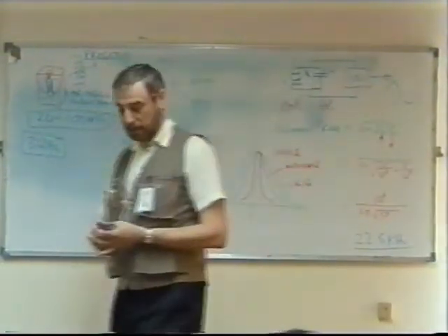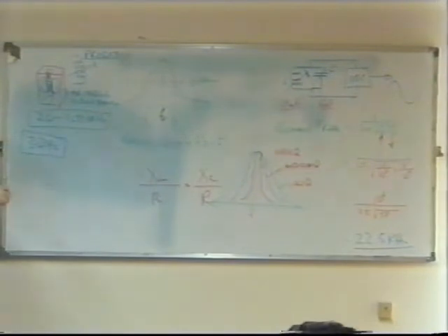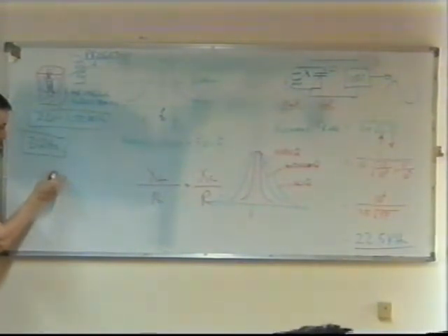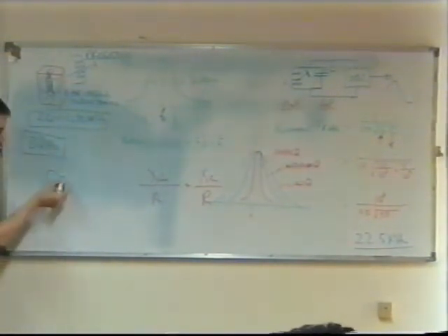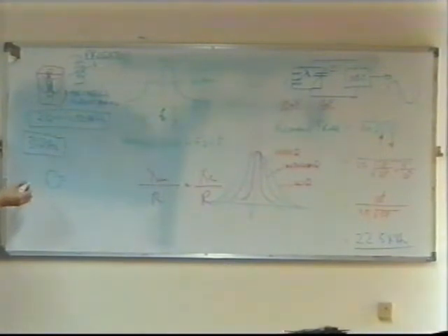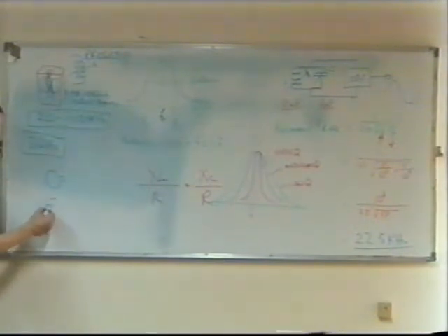Okay, the way they do this with microwaves is this. They get a small piece of wire and they bend it into this shape. And that is a tuned circuit. That's an inductor capacitor circuit about so big. The gap between the ends of the wire forms the capacitance, and the length of the wire forms the inductance. It's equivalent to this sort of circuit, except the values of L and C are exceptionally small and constant in this case; you can't change them. Now, this is what I'm going to come to now.